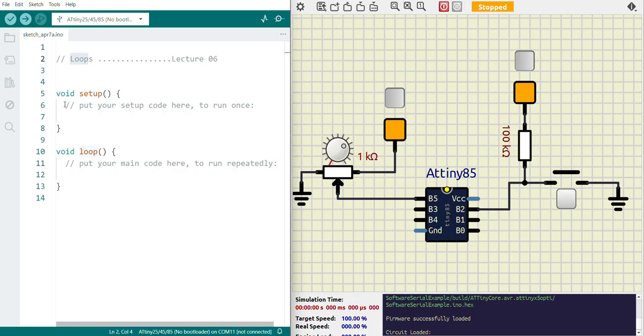So that is equivalent to coming here and saying, let's label PB2 as the button pin, or the switch pin. Let's call it button pin. That GPIO is a whole number, an integer, so we can represent it with an int. So we can say button underscore pin.